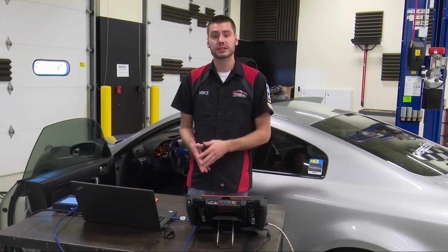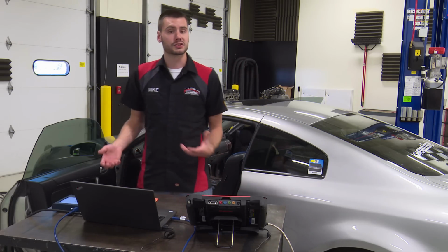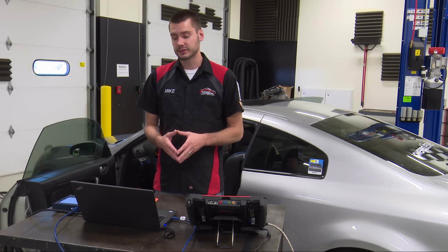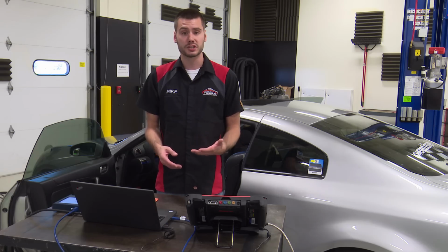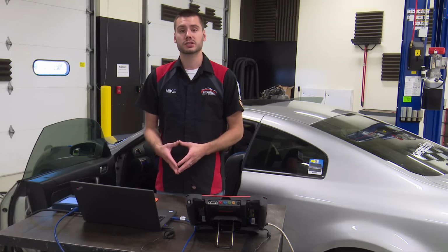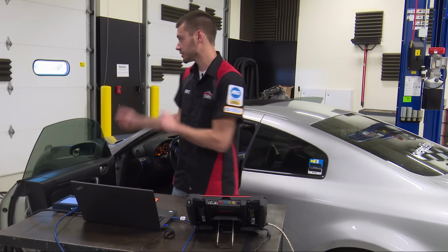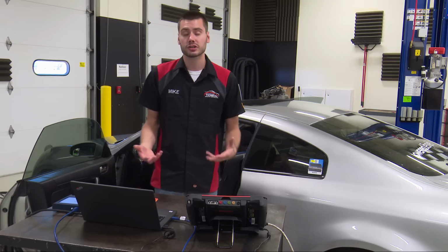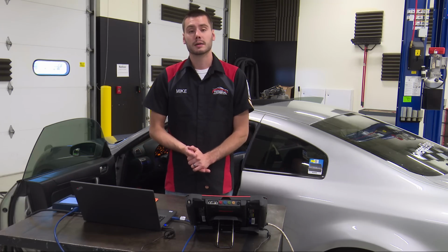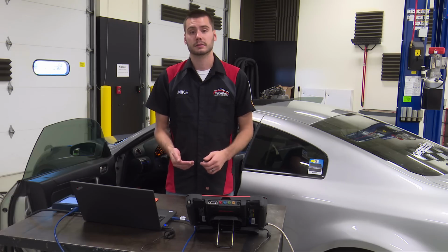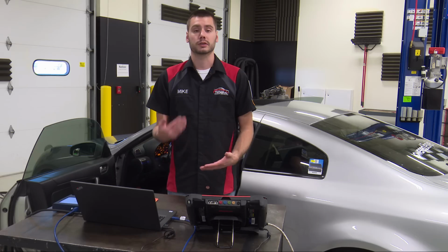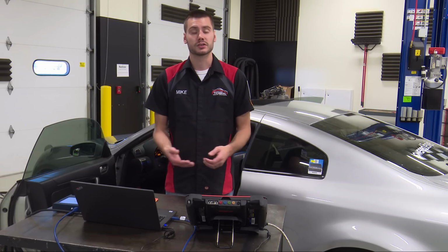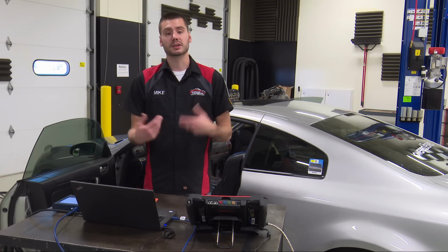So how many of you are actually using a lab scope and an amp clamp and scoping out the current for each window motor when you're doing a diagnosis like this? If we chose not to do it at this point, if we would have stopped once we diagnosed the switch is bad, it's failed, put a new one in, gave the vehicle back to the customer, ran it out the door, the customer would have been happy, right? The window works, it was functioning up and down with this new switch, it was great. But what happens after 2 weeks when the customer's back? Because it fails again. That's what happened with this one. The owner put in a window motor, put in a window switch, and then 2 weeks later, the switch failed again. The problem here is the cause and effect, right?